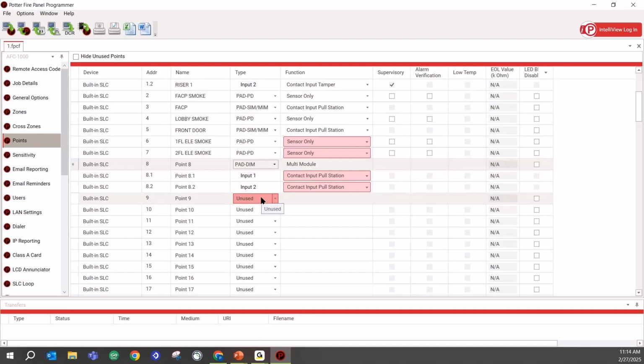They did put a couple of caveats in there, one of which says that you can cut in an access panel. Let's be honest, that's kind of ridiculous. If you know anything about how elevator shafts are built and the fire rating that they have, cutting in an access panel is a very expensive conversation. So what we can do is we can put in non-serviceable elements into the shaft, and then the serviceable elements would be in that easily accessible space.